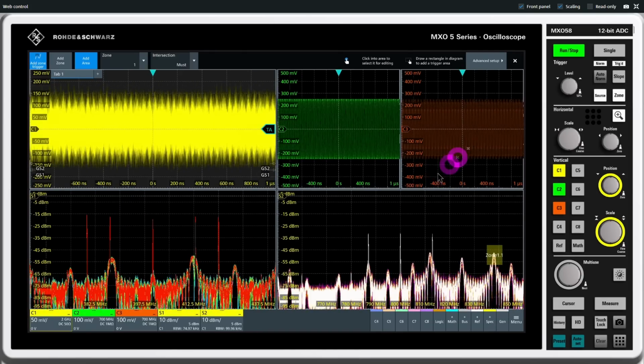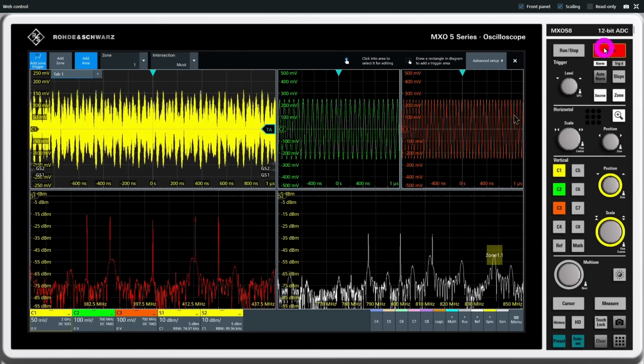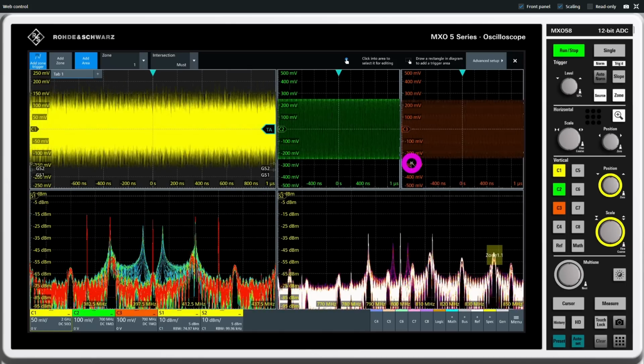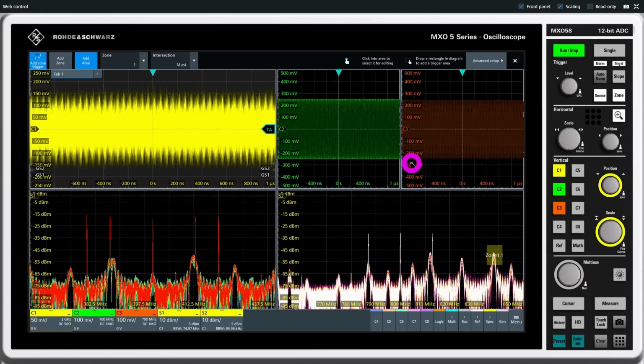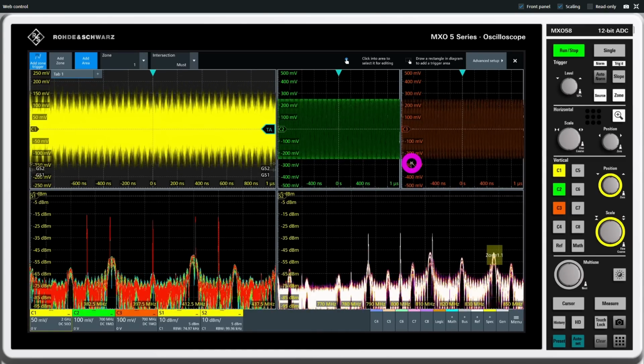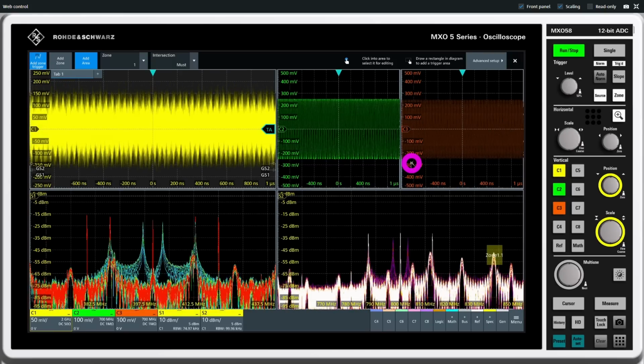If you think about this, what we're doing is that we're always triggering at a point where this tone is present. Now, this tone every once in a while is going to coincide from the time that we're jumping from this frequency to this frequency. And every once in a while, they beat with each other and essentially alias with each other. And you see those two tones. So we have a rolling window of this gating FFT that sometimes lands on that transition.